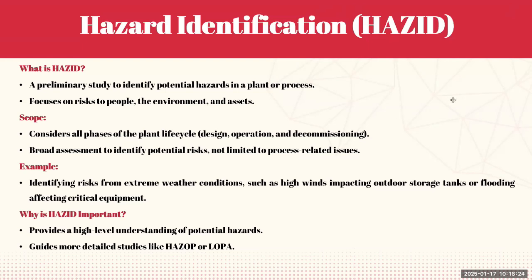So why is HAZID important? It's because by providing a high-level understanding of potential hazards, HAZID lays the groundwork for more detailed and targeted studies like the HAZOP or the LOPA, which we'll be talking about shortly. It's basically the first step in ensuring that no risks are overlooked. So in HAZID, we ensure that we identify all the risks that are general to the process plant.